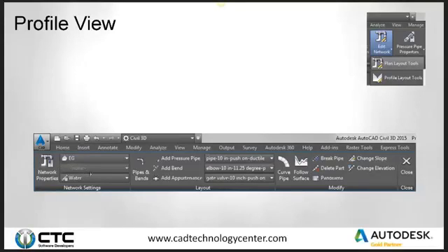What's my target surface? If I have an alignment, I can target an alignment. And then what's my parts list? I can add pipes and bends. I can add specific pipe, I can add specific bends, I can add specific appurtenances. So this does the pipe and bend.